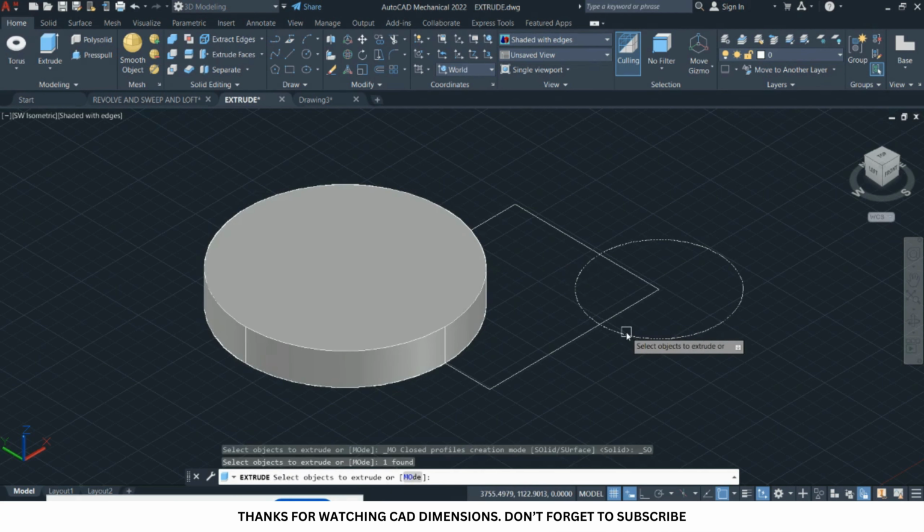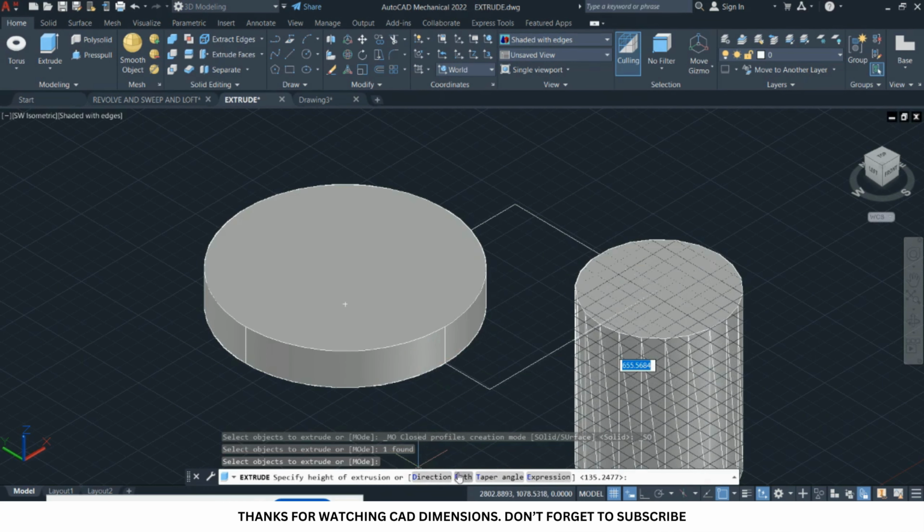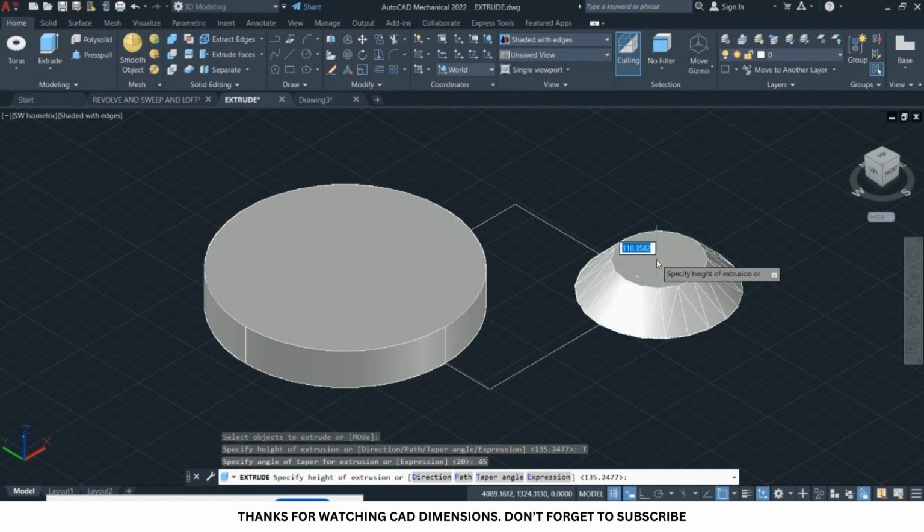Okay, so if I click and I press enter, now we have the direction, we have the path, we have the taper angle, we have the expression. Let's look at the taper angle. Okay, you can try the path and direction and see how it goes. So select taper angle, then let me enter a taper angle of, let's say, 45.